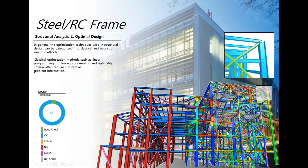By looking at the contour in the program itself, we can understand if the design results are passing or failing, and then accordingly we can go ahead with the optimization. Basically, optimization is where we try to make the members be in a given target ratio, like 0.6 to 0.9. Alright, we'll go ahead now.